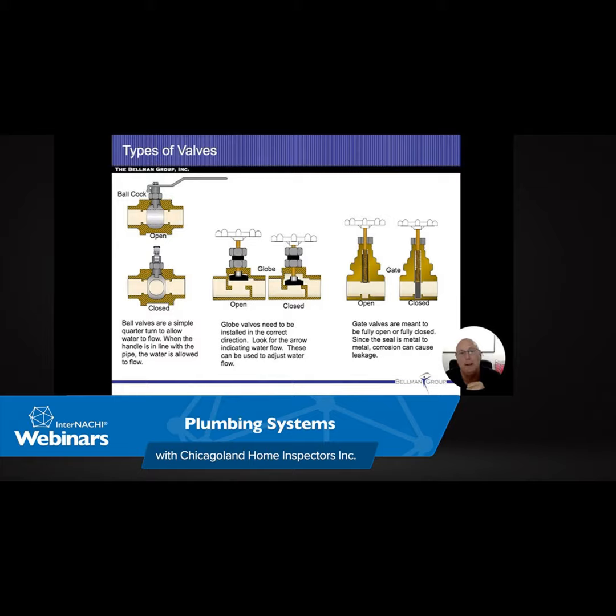If they're different and in different directions, water flow and friction loss all has to do with pressure differentials. So if I have the same pressure on both sides of them, water's really only going to flow down the path of least resistance. So you're going to end up using one water heater.